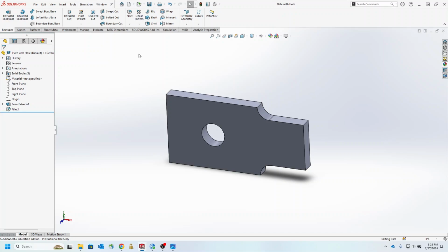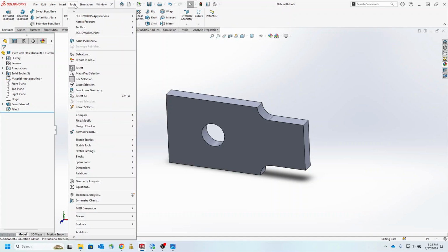So far that is what we have done. So you should have a simulation tab here. First of all, you have to add it in, as the required add-in option. If you haven't done so, go to the tools and add-in menu, or you can just drop down the menu of the setting icon here and go to the add-in function.